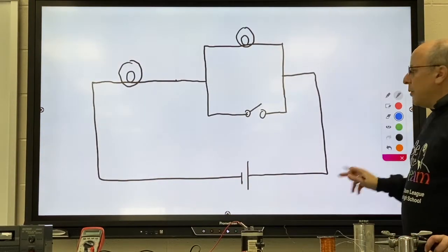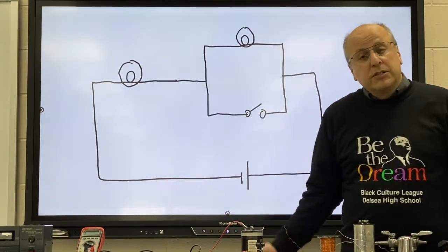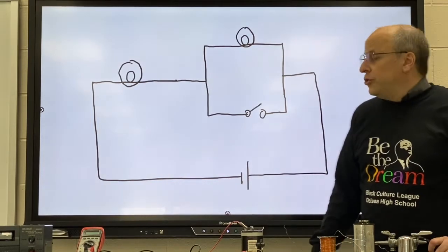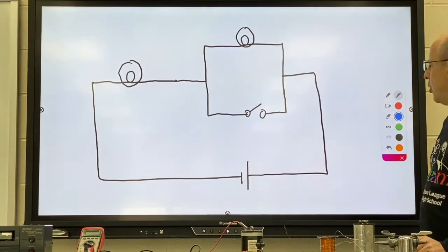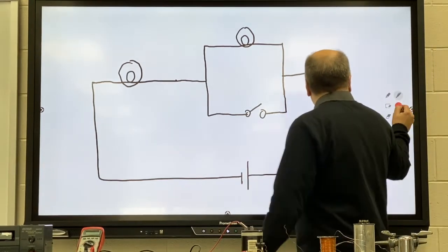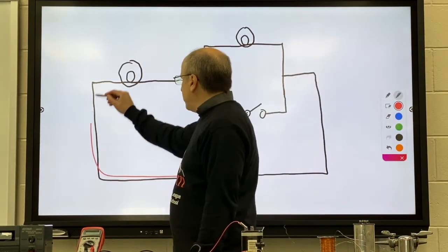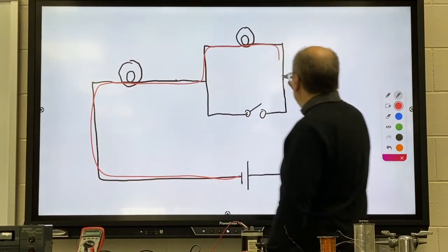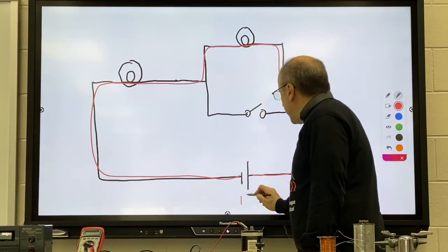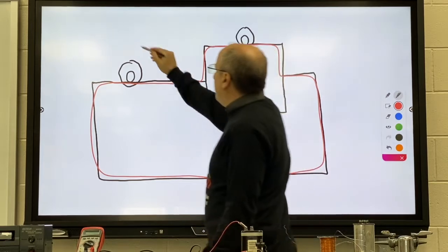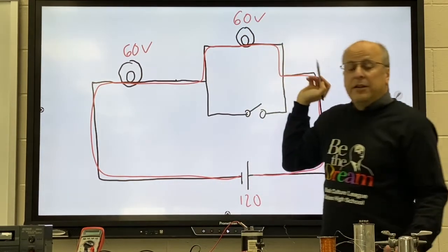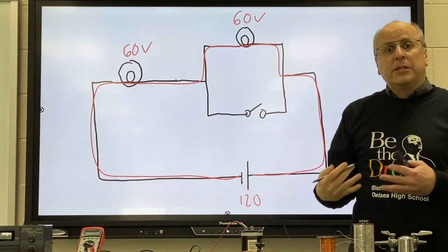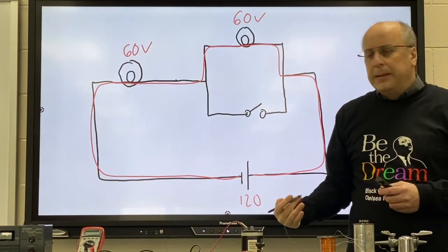The final thing is I want to make sure you understand short circuits. We saw this really briefly in this unit, but it's something they like to ask you about. So with that switch open, we would have a series circuit with these two light bulbs. And if they were identical light bulbs, that means each bulb would be getting 60 volts. They're designed for 120, so they'd be much dimmer than they're supposed to be.